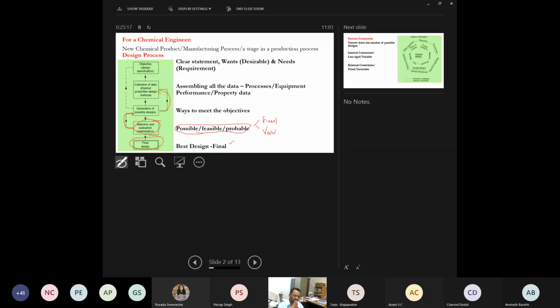Again, if you give more than 30-40%, in such cases your equipment size will be bigger than the required one. So automatically it increases the capital cost. If the size is big, automatically your operating cost also will be more. In the initial stages, when processes were developed, the concept followed was 'big is best', so the process plant would be the bigger one.